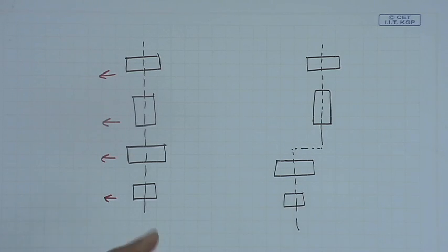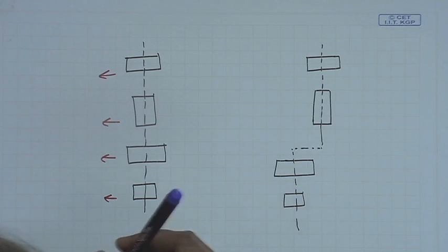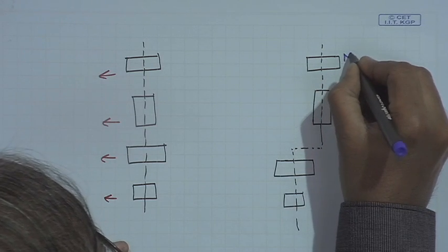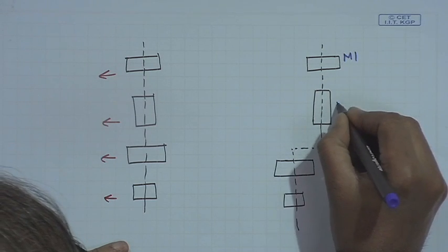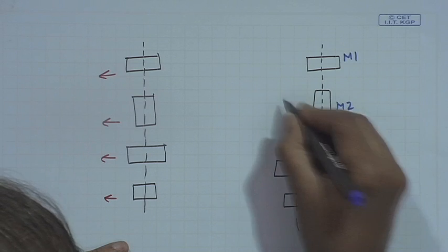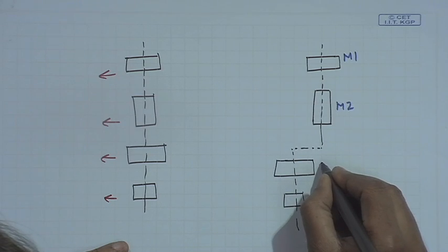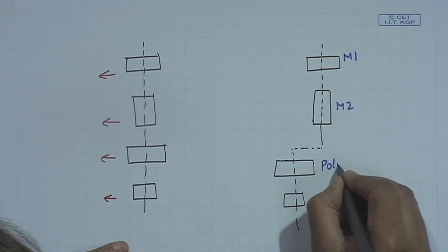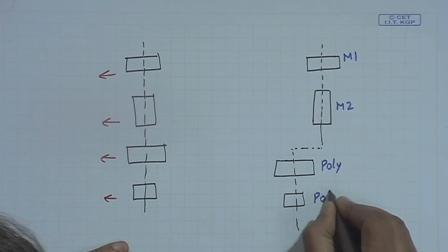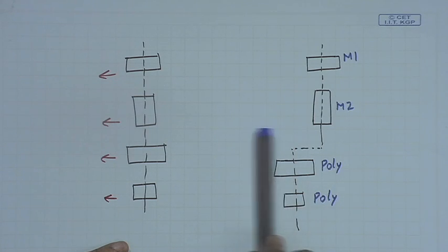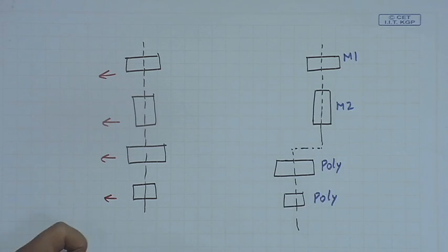Let us say it is possible that these 2 are blocks in the metal layer which has higher distance constraint, but these can be polysilicon layers. Polysilicon has separation of only 2 lambda. So, maybe this can be shifted together, but not these, right. This is the basic idea.